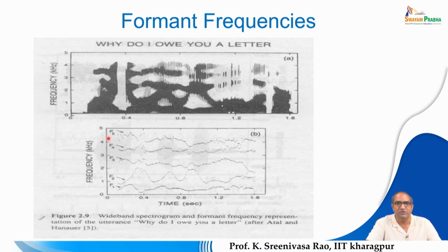So for deriving those frequency ranges, instead of a range of frequencies, we will take some center frequency or a mean frequency of the band, and then we will track that. For every frame we will try to identify how the energy is concentrated, and we will take 3 or 4 dominant frequencies where the highest energy is present. Likewise, for every frame we will compute the dominant frequencies. Here the dominant frequencies means the frequencies where they attain the highest or maximum energy.